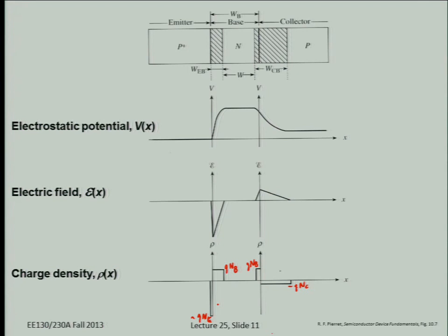Okay, so qualitatively, you should know that the slope here is proportional to minus Q, to the charge density, right? So it's minus Q N E. That's why it's very negative, and it's steep, much steeper than this positive slope here. So just remember the slopes are dictated by the dopant concentrations. And then you integrate the electric field distribution and invert it, with the negative sign, to get the electrostatic potential profile. Now, the electrostatic potential profile just looks like that band diagram, but flipped.